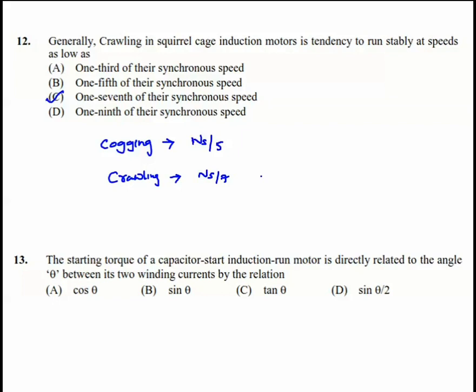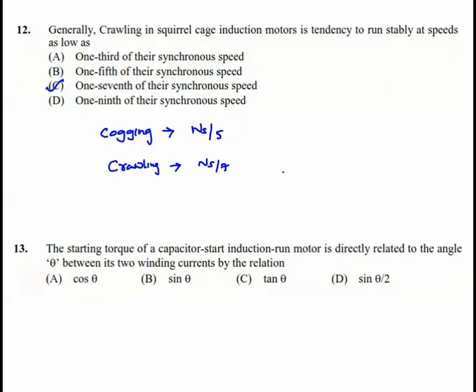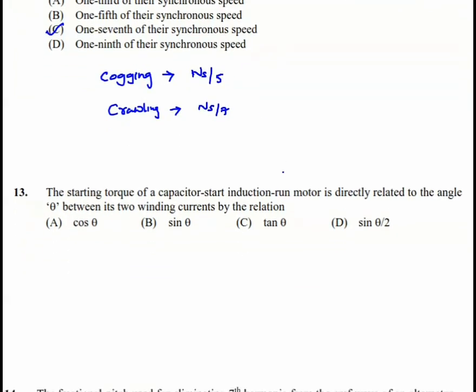Okay, and the next question, it's a very simple question. The starting torque of capacitor start induction motor is directly related to the angle theta between its winding currents by the relationship. So the direct relationship is T is proportional to phi 1 phi 2 into sine theta, where theta is the angle between these fluxes phi 1 and phi 2 here, and the answer is B here.